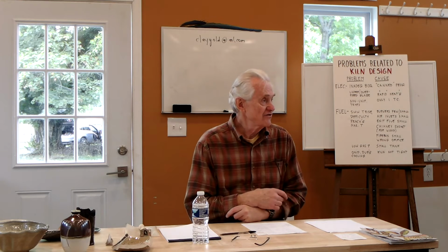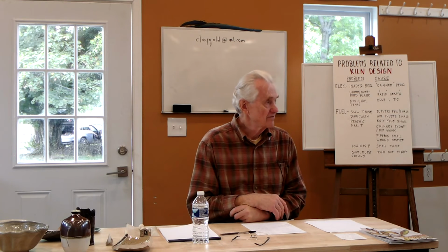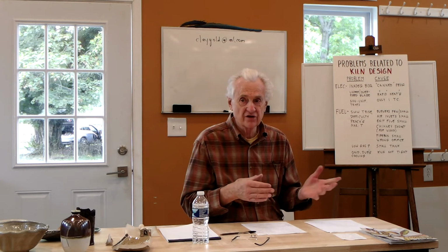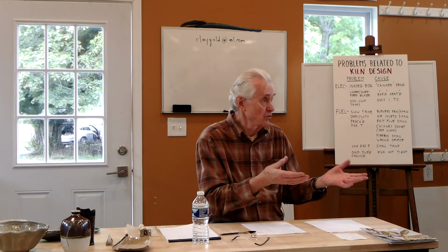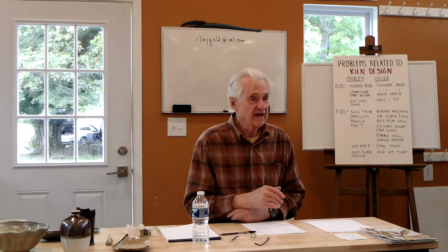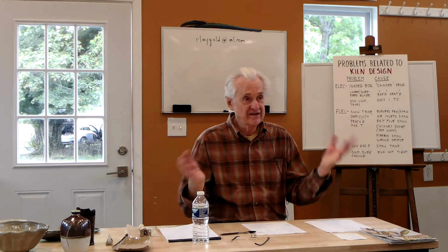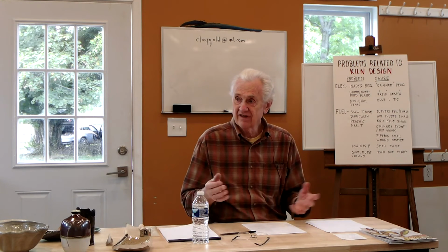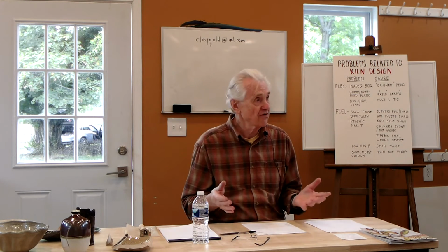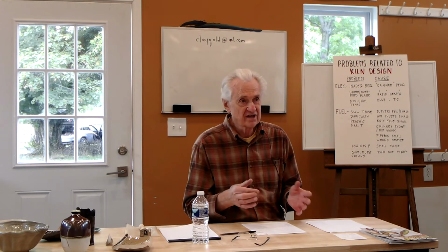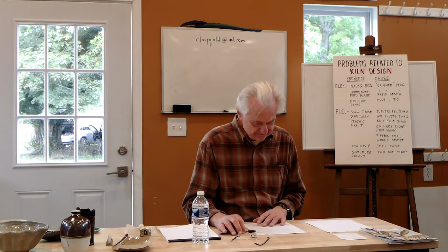Yeah, you can't. And sulfur and all that get burned out. Right, and so there might be a point where you need to hold it. And with the clay you're using, the only way to find out is to try it. So in that case, the canned program is inadequate. And I've seen that happen where people say, well, I used the standard program. Well, in that case for their clay, the standard program wasn't appropriate. They needed to modify the program because they were using not your typical average clay.